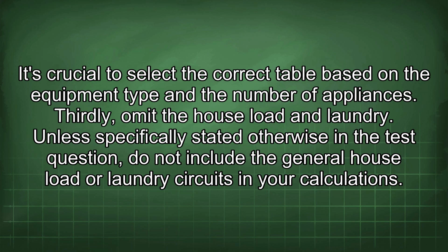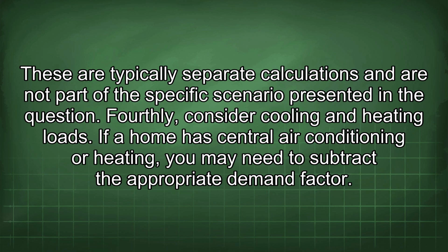Thirdly, omit the house load and laundry. Unless specifically stated otherwise in the test question, do not include the general house load or laundry circuits in your calculations. These are typically separate calculations and are not part of the specific scenario presented in the question.